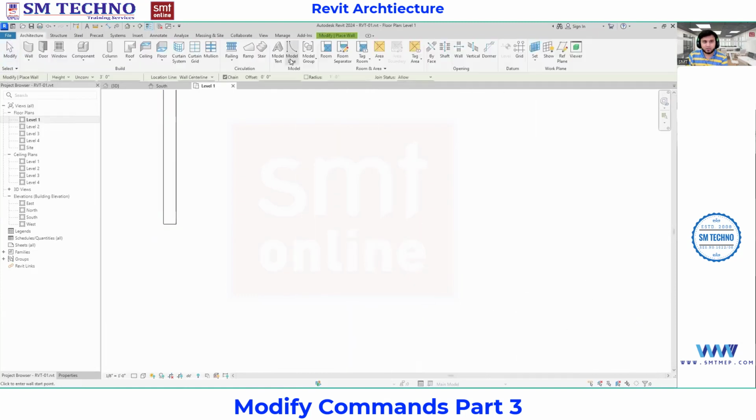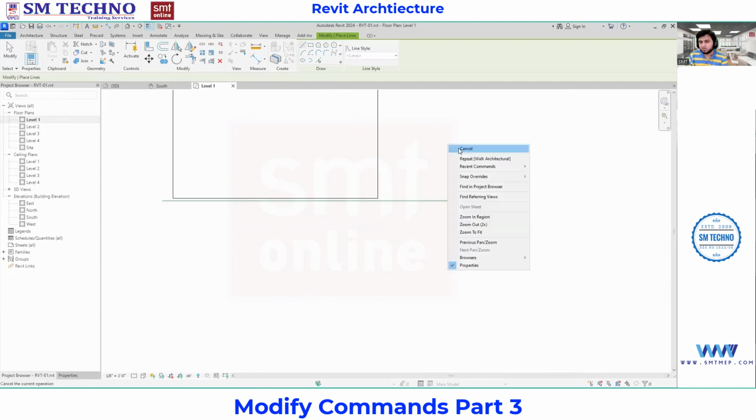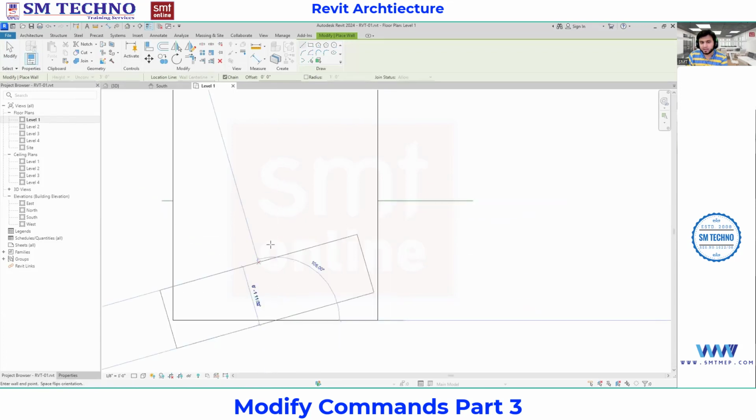So what I do is I'll go with an offset. I'll provide one model line which is less than 0.16 mm from here to here. This is only a reference. Why have I taken this? Because I want some median, a gap between the two walls. So again, I'm going to select the wall. From any point of view, you can sketch this. So can you see we have got a gap?